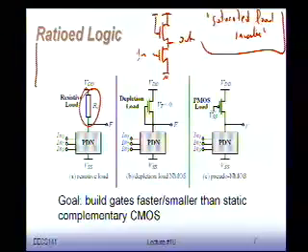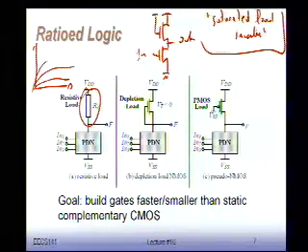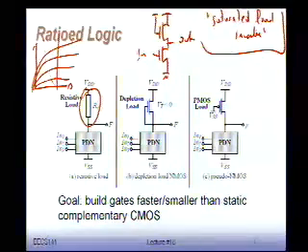So if you look at the load curve of this device, you have your NMOS device running like this. The load curve of the NMOS device is going to be inverted here, and it's going to be sitting like that. Okay. So it's quadratic. It's a saturated load. If you put on the equations, you're always at the edge of saturation there, you will see that you get a quadratic kind of current dependency, if you don't assume velocity saturation.